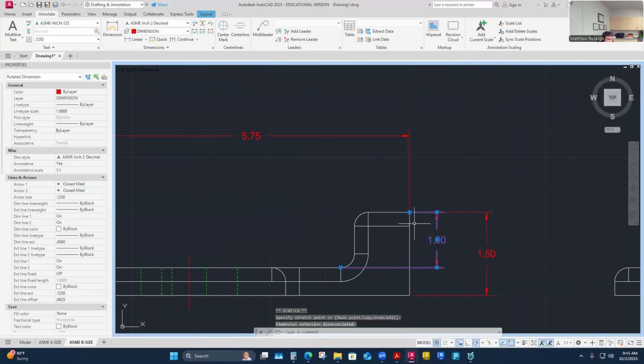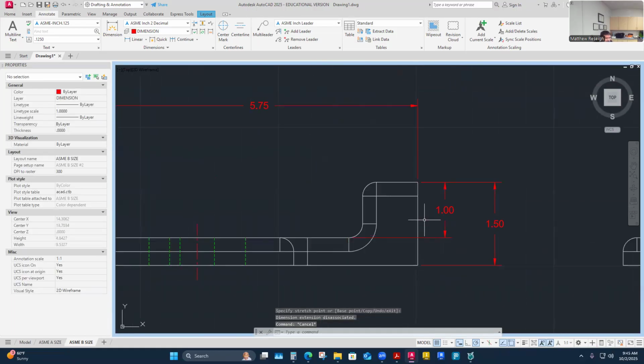I've corrected a few people. This is totally allowed. I definitely pull back this one to the object edge, but if this feature I need to reach out and go across my visible line work, that's actually okay. That's permissible with my extension lines to do that. Maybe I try to minimize it, or maybe there's another view where I don't have to do that, but it's not like it's a good practice.